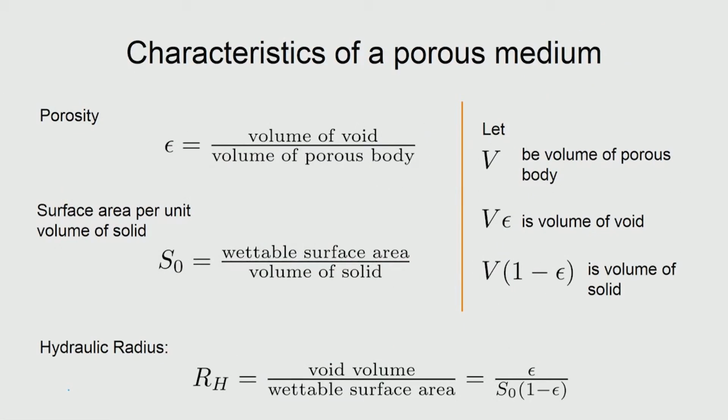So here we now introduce some terminology to characterize a porous medium or a porous body, so that this will be useful for our derivation. One characteristic of any porous body is to tell how much porosity is there. So you should tell the porosity as the first characteristic. If you take, for example, a powder bed and you are using powder metallurgy principles to sinter it to a solid block, then depending upon the extent to which sintering is happening, you would have porosity changing.